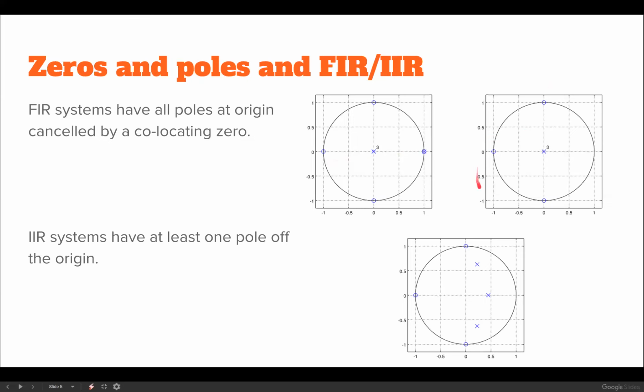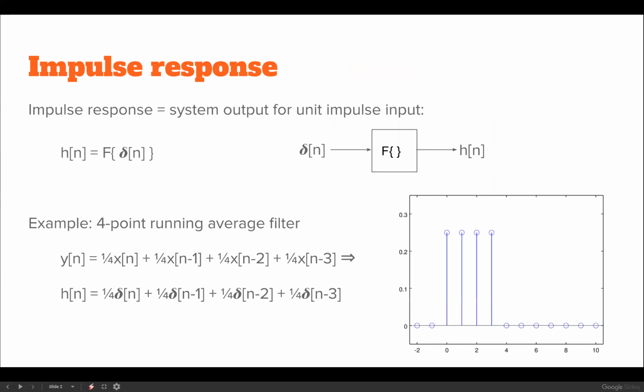This is the straightforward case of feed forward only, where you have more calculations. Then we have the zeros on the unit circle. And then we have a triple pole at origin, so it's a finite impulse response system, as we could actually show it already here. The impulse response stops at the fourth term. It goes to zero and stays at zero.